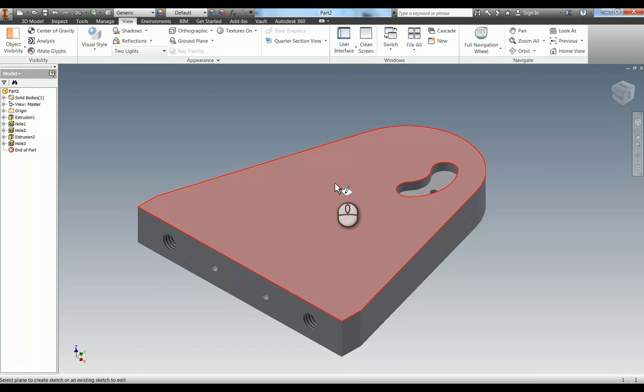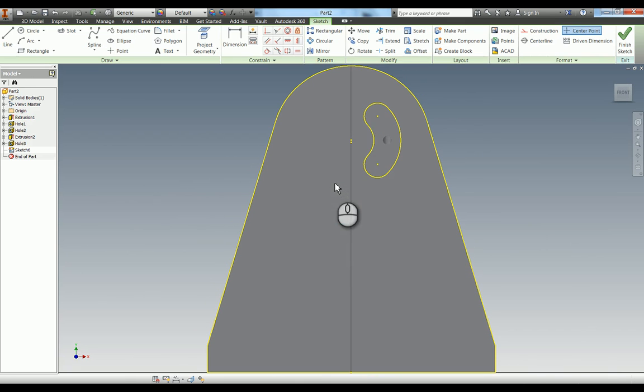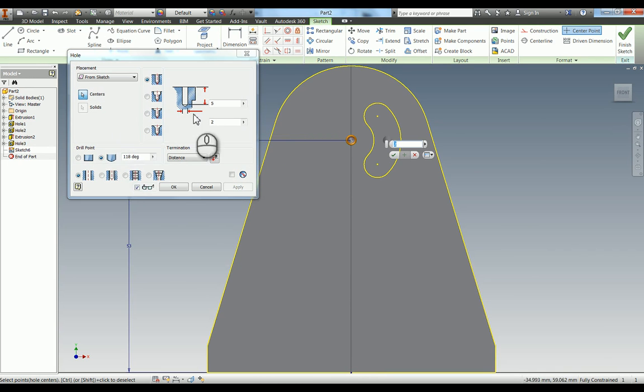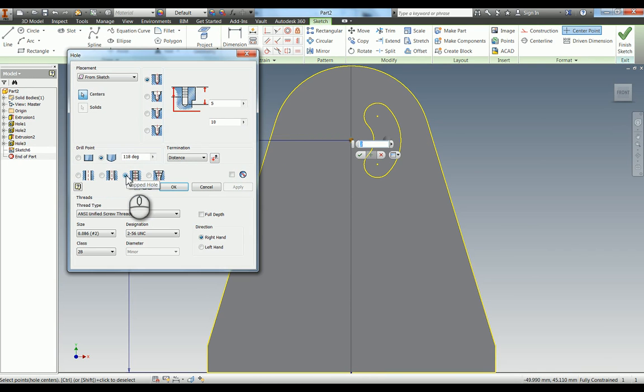So we've also got another hole that goes through the centre here, and again you make sure you get it on the right area. So just to be sure, I'm going to put a point down, and I'm going to dimension it rather than putting it on one of those, and that's at 53mm, and it's vertically aligned with the midpoint, and this is actually an M5 through all. Again, make sure you get the correct designation. That's not distance, that's through all, and the thread is full depth.